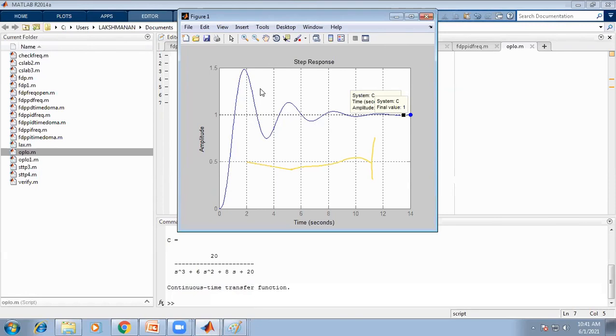So now I'm using a PD controller. What I told is that when I introduce the PD controller, the overshoot will be reduced. So now let me check. Actually, the system without a controller, in closed loop response, reaches the final output, but you check the overshoot, it is high. Let me check that overshoot. 48.3% is there. So now I'm going to reduce that overshoot by using the PD controller.